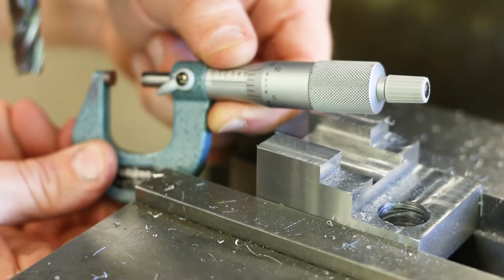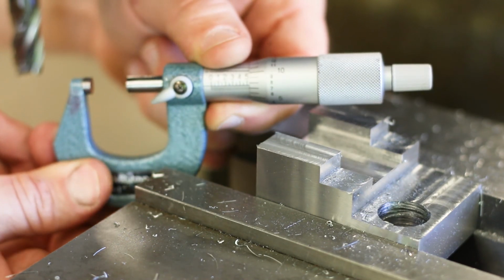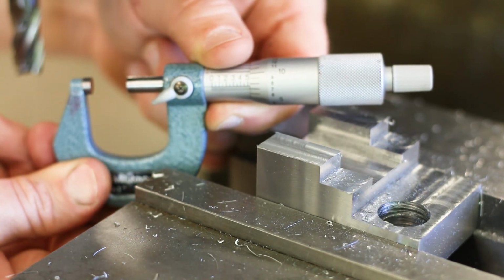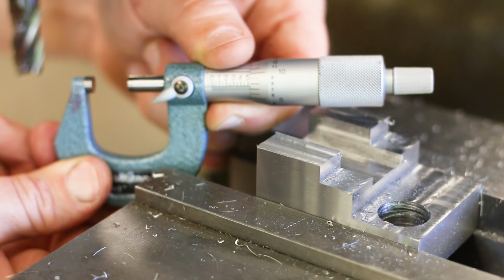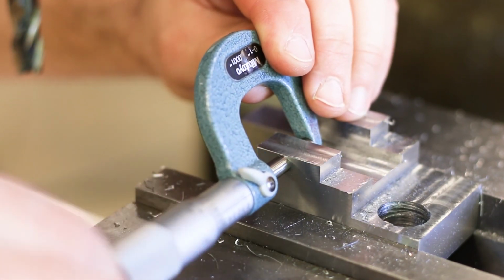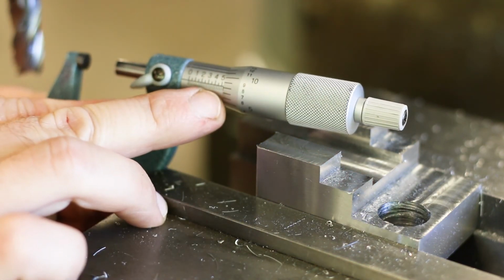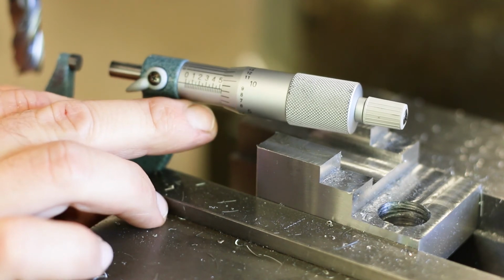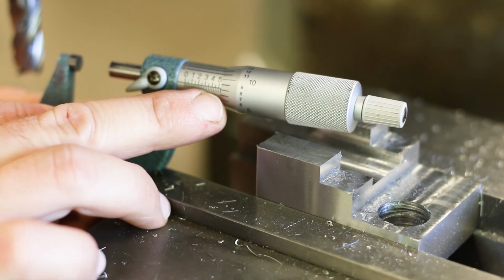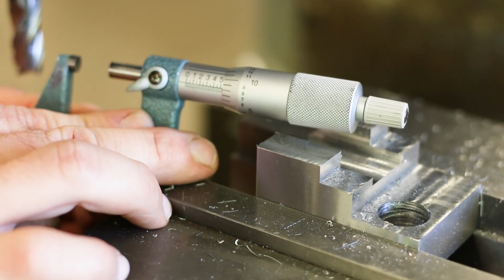Okay, let's take a measurement and compare the two sides. This side says 525 thousandths and 7.5. So 1 inch, 532 thousandths and a half. What about this side? 1 inch, 525 and 8.5. So 1 inch, 533 and a half. So we're about 1 thousandth off.